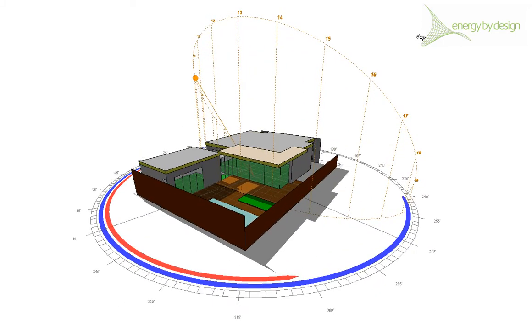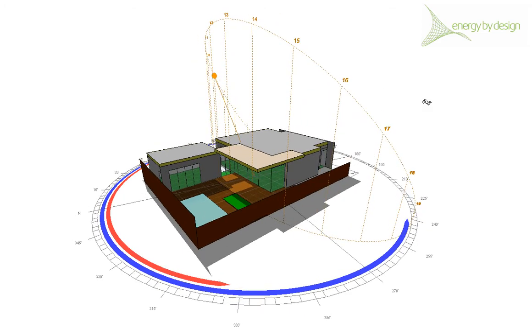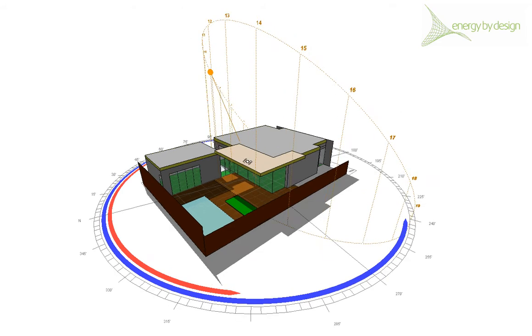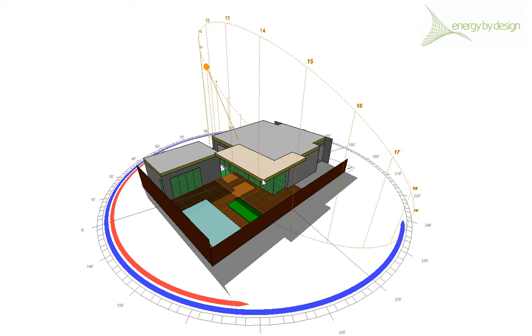Okay, so the important thing we're looking for now is to prevent sunlight, particularly during the mid and later hours of the day, from entering our building, because being summer, with quite warm temperatures, we're looking to minimize the heat gain. Here in particular we're going to look at the effect of this, it's actually an adjustable pergola in this building.